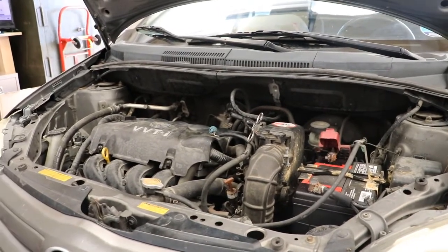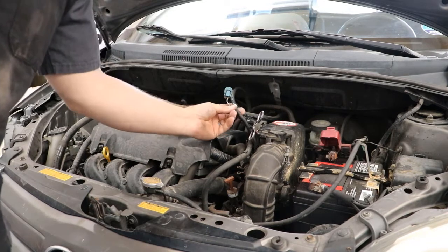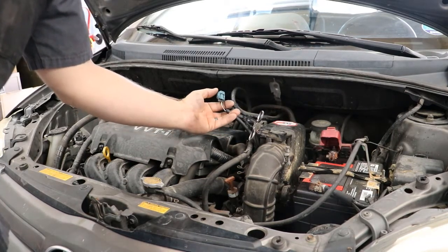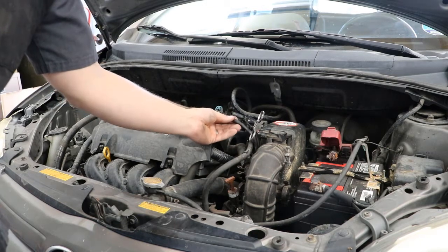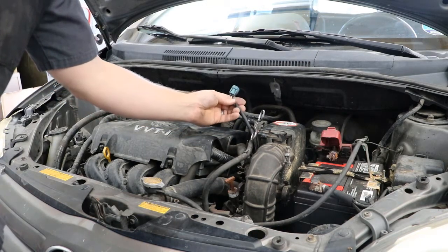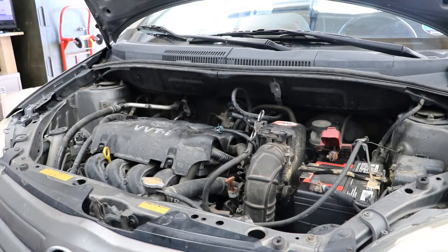So what we're going to do is replace this connector in the front here. Simple connector problem here. So this connector I'm going to replace. Going to buy a new connector head and just recrimp on and connect these wires. Probably get some shrink wire and make sure it's a solid connection. Reclip it on, clear the codes, dry it for a bit, and that should fix the problem. And yeah, that's it, guys.